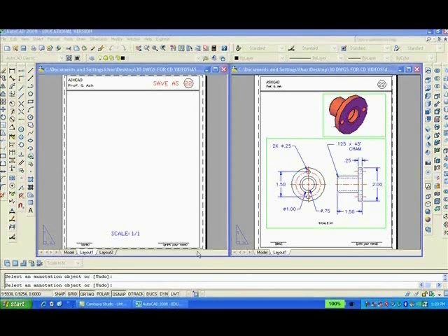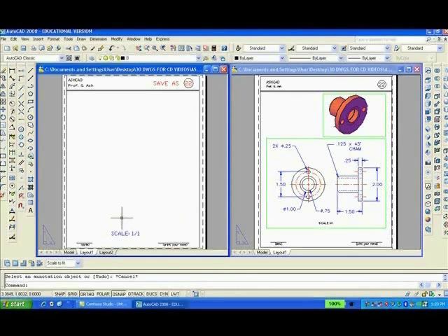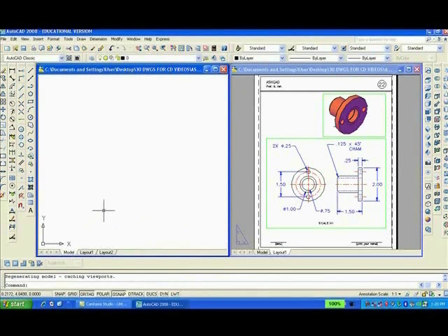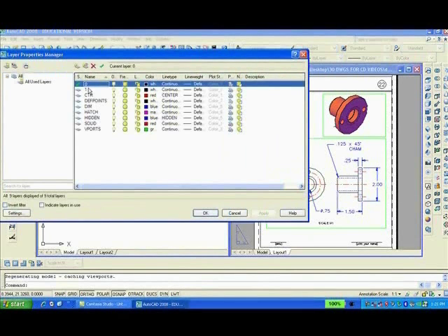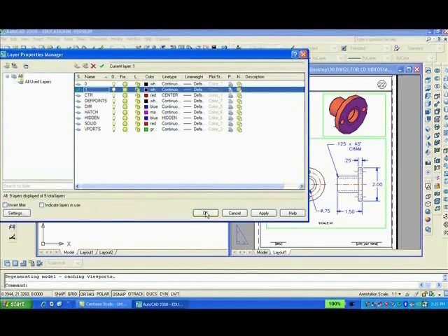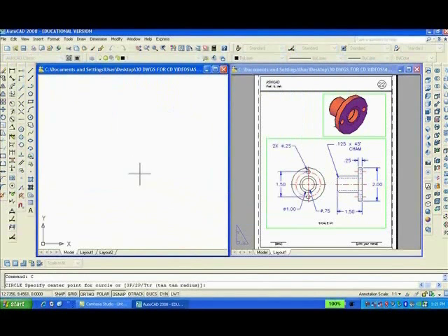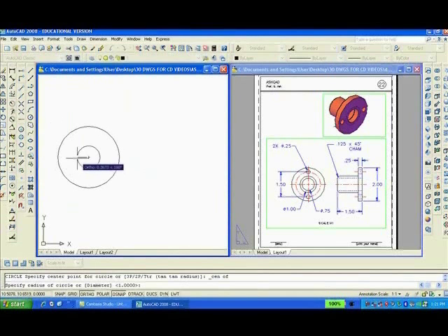Hello again. Probably a good idea to start this drawing off with some concentric circles, but of course we have to go into model space. We have to set the layer 1 to be current. Then I can type C enter, pick any point, C enter, 2 enter. Enlarge the view. I can type C enter. I can snap to the center and type D enter, 0.75 enter.